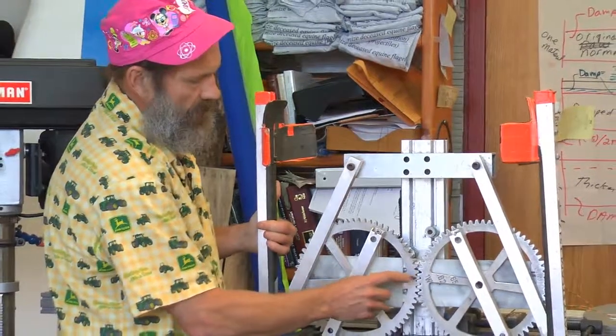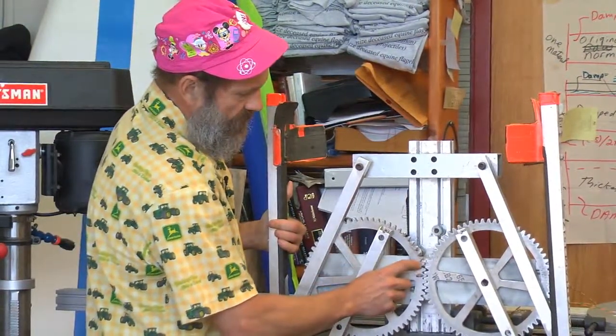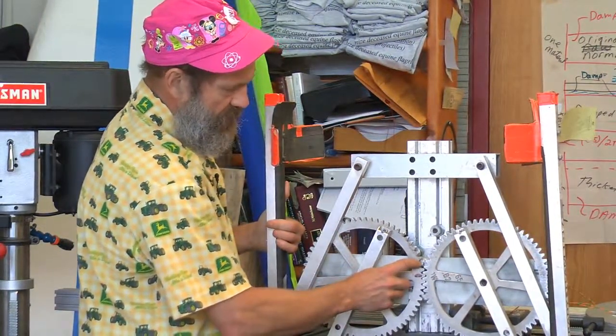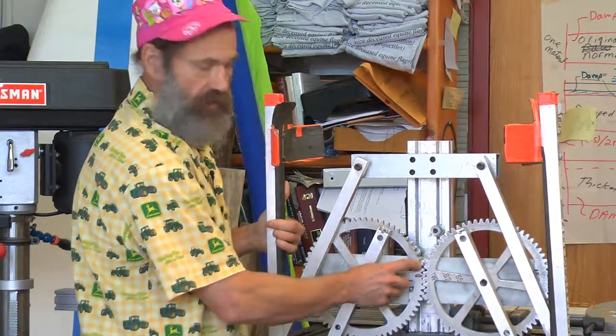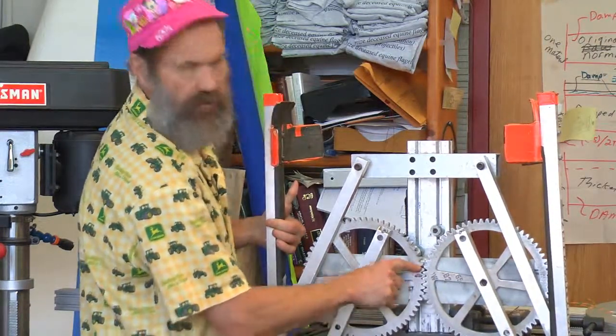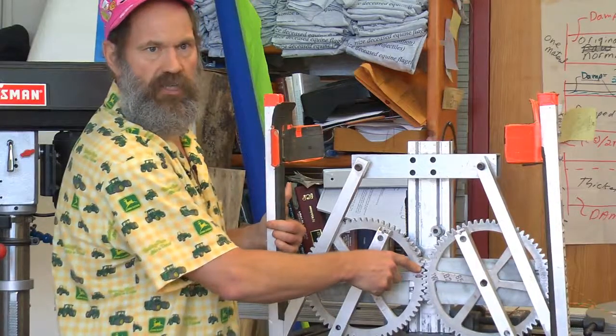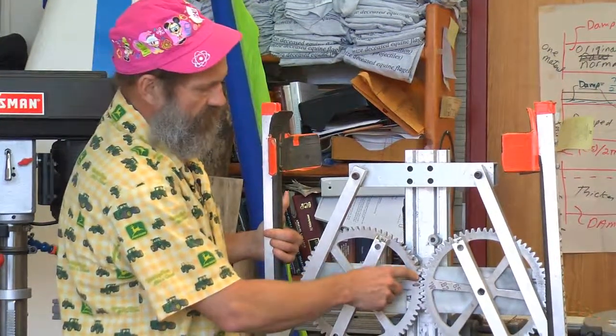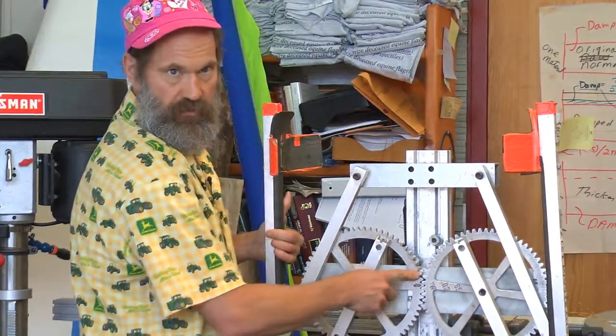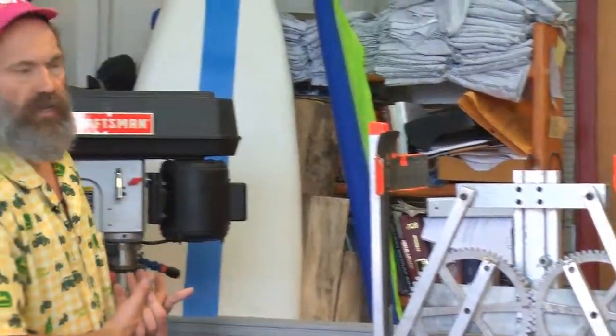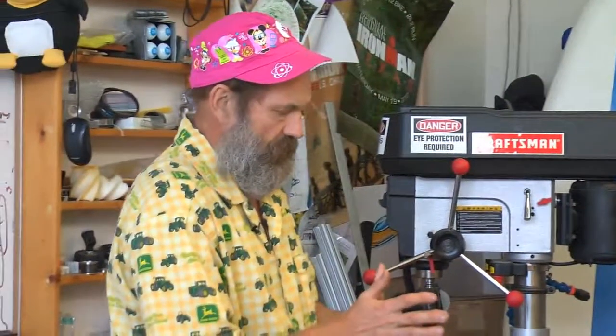Well, it turns out using energy methods, you can calculate the deflection due to the bending and the shear as a function of the varying cross-section of the tooth. Very straightforward to do. And now you have your closed-form solution for the stiffness of that gear tooth, and that would allow you to determine the stiffness of your rotational mechanism governed by those gears. It's stiff enough.